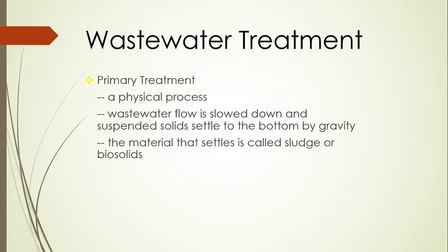In the wastewater treatment, primary treatment, after the preliminary treatment, water enters into the primary treatment process. In this process, mostly the physical processes will dominate. We will target the removal of further smaller particles through mechanisms such as sedimentation. We try to settle the particles which can be settled readily from the wastewater.